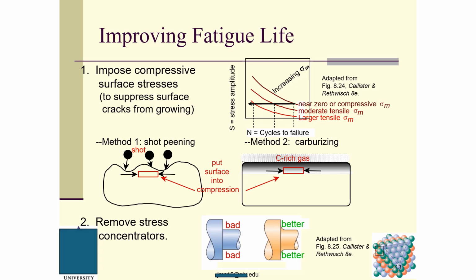However, tensile residual stress facilitates the crack initiation and crack propagation. As a result, tensile residual stress is detrimental for the service life, for the fatigue life of the specimen. I want all you guys to write this down. So first is shot peening, and this is traditional shot peening.